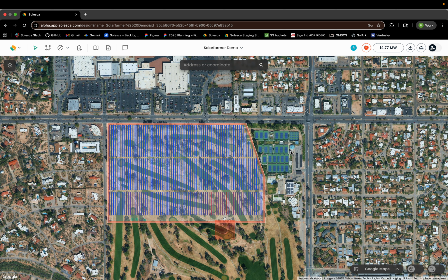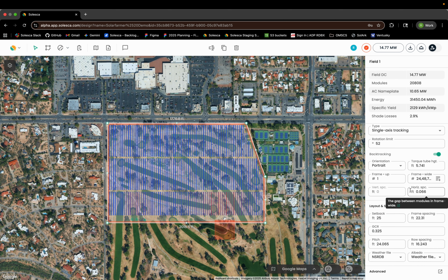Most of the time that discrepancy is either going to be there or in the near shading. So we allow you to do those object obstructions. We allow you to do those trees. If you get that right, you're going to have extra losses compared to using, say, PV Watts, which does not incorporate any of that. So those are the three pillars. You've got the model, which is SAM or the bankable DNV Solar Farmer. You have the layout itself, which is up to you to make as best as you can. We provide those templates and then you can deviate from them. And then you also have the assumptions, and we provided those bankable assumptions for you to use, and then you can deviate from them at your peril.